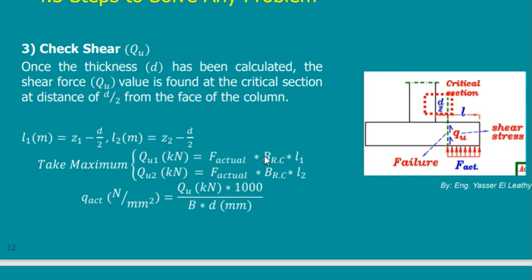So we have to check that our foundation, when we put it on the ground, part of it is not going to be separated due to the load, and the column is not going to penetrate the foundation and leave the foundation alone. So penetrate means punch, so this is punching, and I compare it to a standard value that I cannot exceed.